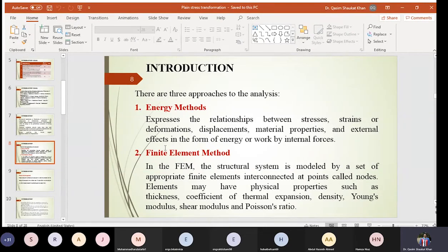So here we will split our element into a smaller number of units. Then we will analyze one unit. We will calculate the normal stresses, shear stresses, normal strains, shear strains, principal stresses, principal strains, maximum in-plane shear stress and shear strain, orientation of the principal planes, and orientation of the shear planes for one unit.